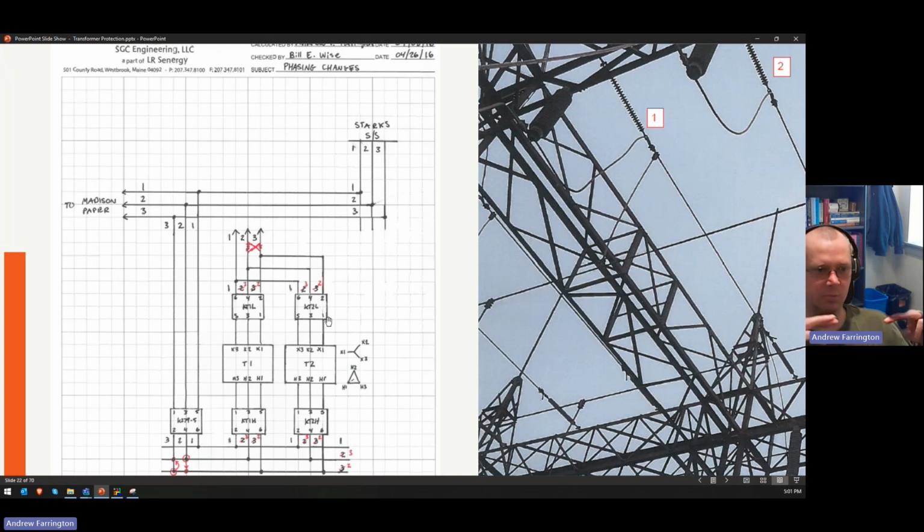And so I was thinking that maybe there was just some sort of rotation issue at the phase. They had brought in 1, 2, 3, and then 1, 3, 2 at the switch. So you can't close it because you tie 2 and 3 together on those two blades. And so you'd have to roll this here, and now it'll phase and everything will be fine. So I said, well, can we change that rotation? And they said, no, it's weird. The phase tracker doesn't know what to do with it. We can't figure out why it doesn't work. And I said, I know what the problem is.